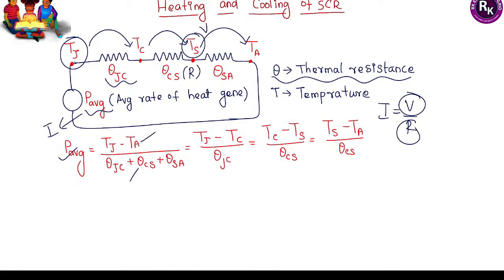You can see I have drawn the complete thermal equivalent circuit. From here, if you want to know the total current, find the total potential difference between Tj and Ta, that is junction temperature versus ambient temperature. So, Tj minus Ta divided by the total resistance. Or you can focus on an individual resistor: the junction temperature minus case temperature divided by the thermal resistance available between the nodes. Similarly, between these two nodes you can calculate, and similarly between sink and ambient you can also explore.